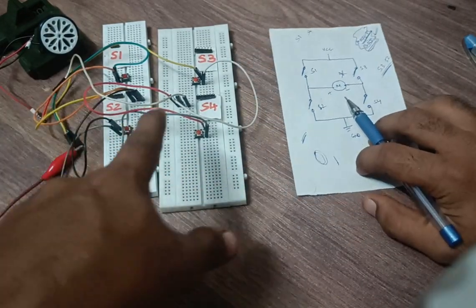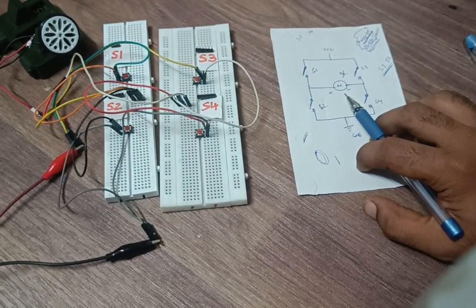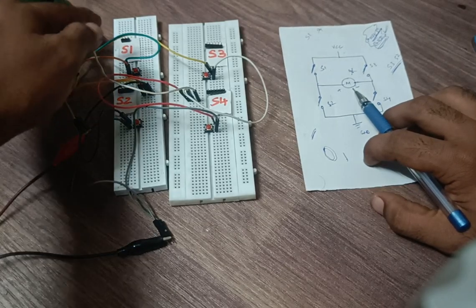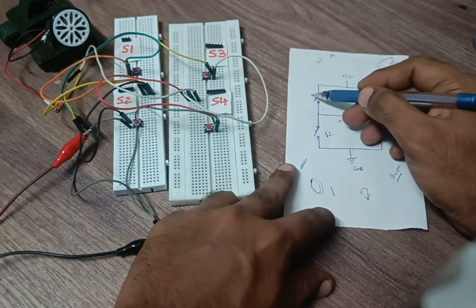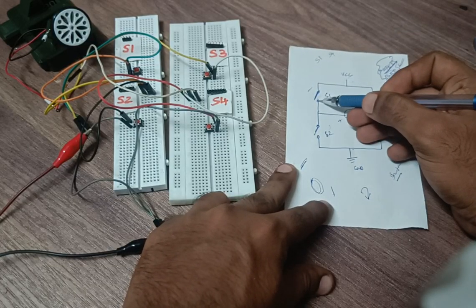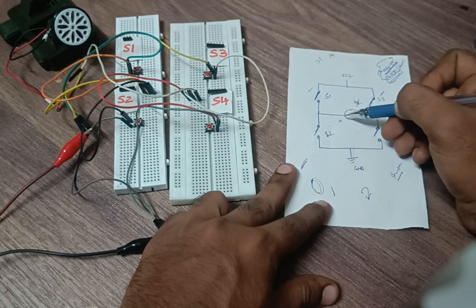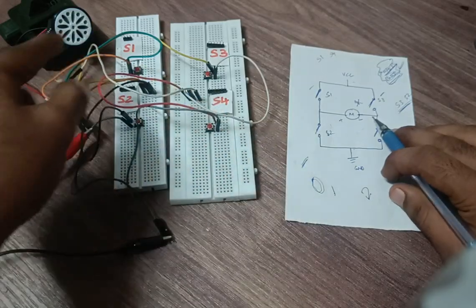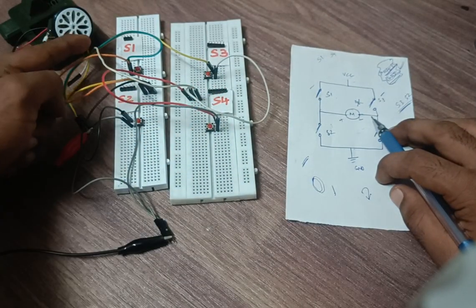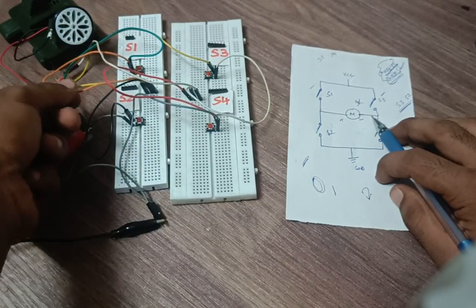The wiring seems very complex here, but nothing to worry about, it's very simple wiring. I'll explain it. The positive is coming from the bench power supply. The positive is coming to the first terminals of S1 and S3. After that, S1's second terminal should be connected to S2 as well as the motor's terminal. So instead of making a wire connected to S2 and connecting again to the motor's terminal, I have made a connection from S1's second terminal, and observe the orange wire.